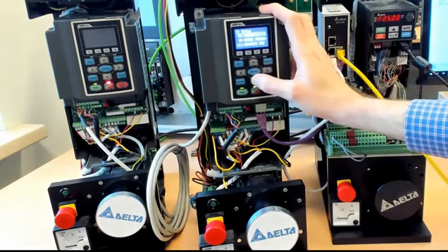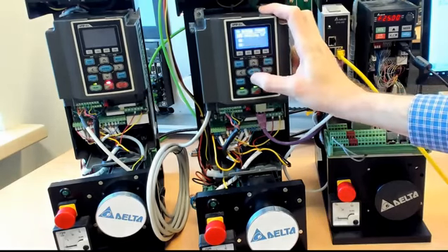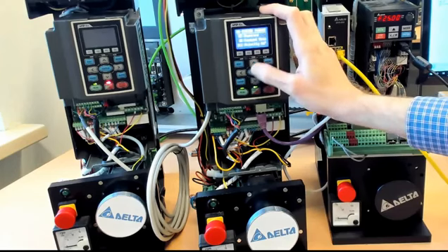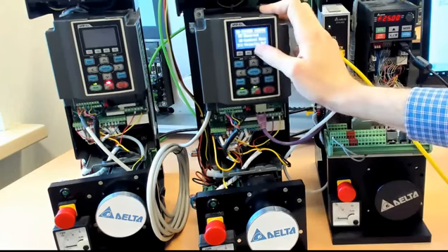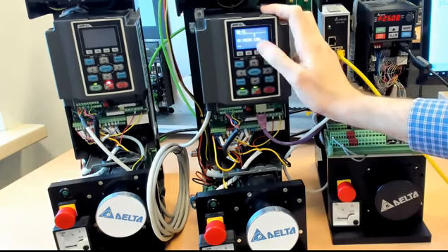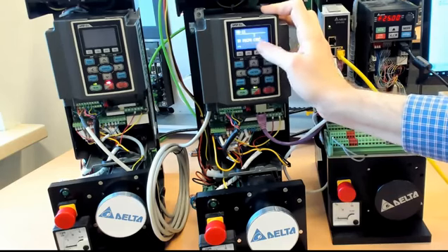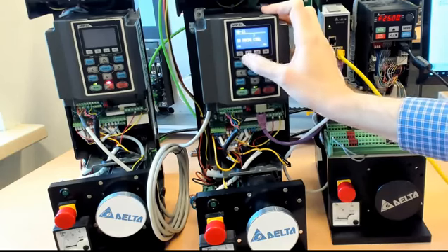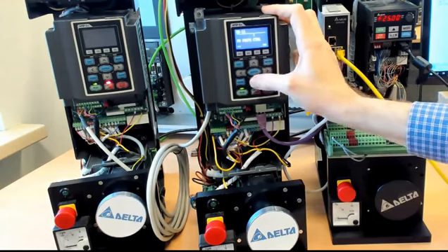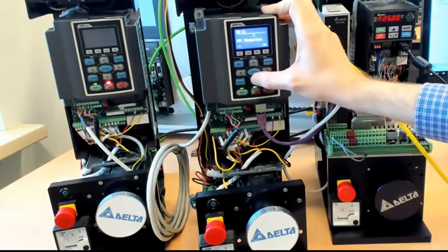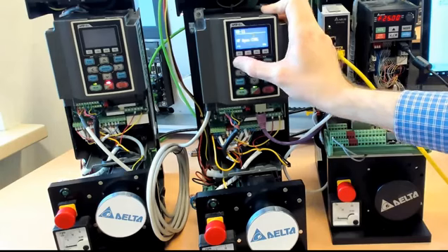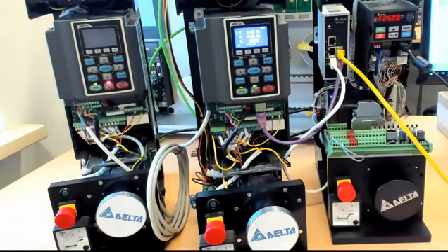So you can only really do positioning with these two modes. So if you go to parameter 00-11, velocity mode, you can only really do it with 4 or with 3. So IM FOCPG or PM FOCPG. You cannot do it with any other mode. You cannot do it in SVC sensorless or VF. So it's mandatory to have an encoder. Okay, so I hope this answers the question.